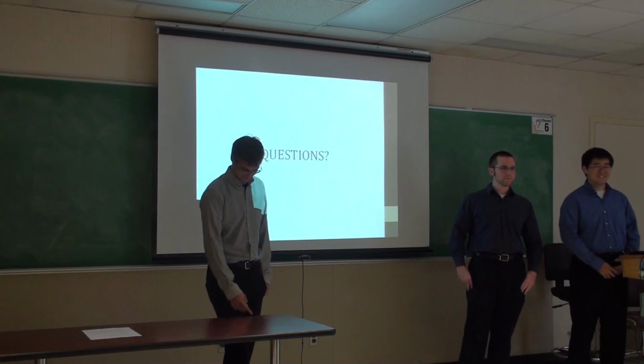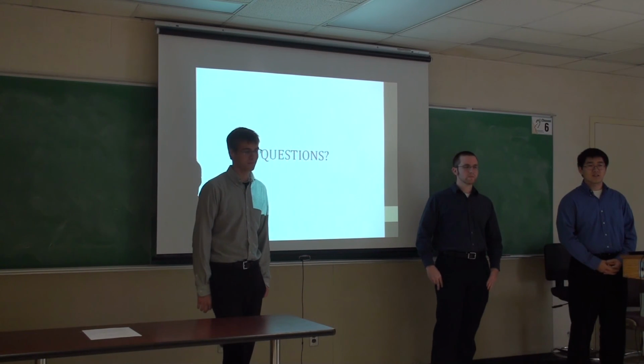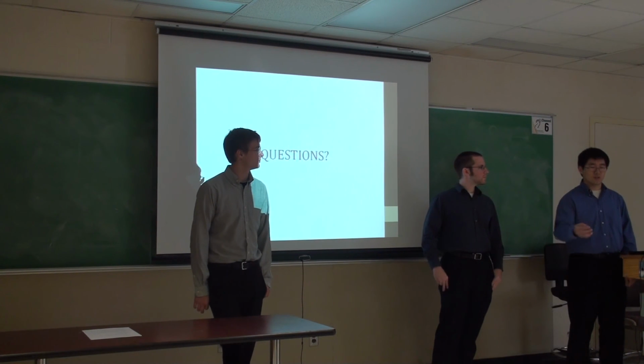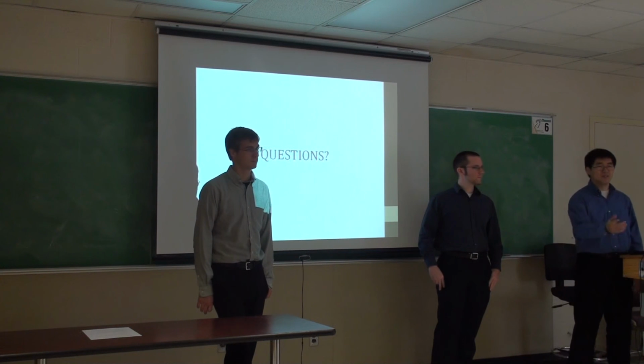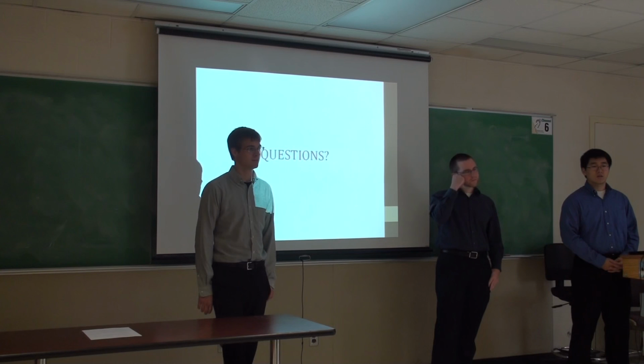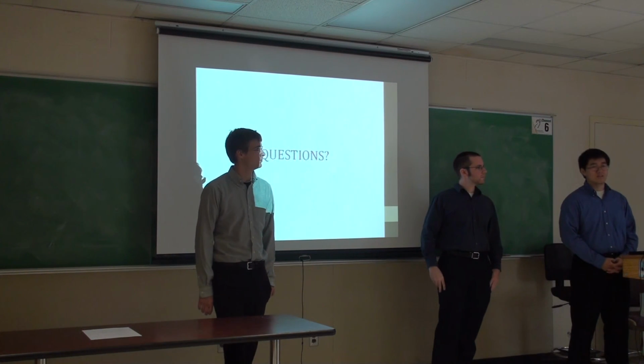You said the accelerometer was ±2 to ±16. Does that include the smaller values? Yeah, there's a bunch of settings in between that you can choose, like ±4, 6, 8, 16. What about the smaller values? The top value is ±16, and then it does the range underneath it. Oh, okay.